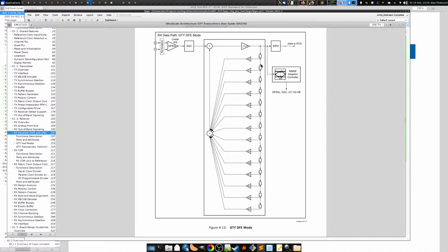Hang on a second. So what do you need for oscillation? You need some delay, and you need some negative gain, right? You need an inversion. If you have a positive gain, you get a positive feedback loop, it runs into the rail. If you have negative gain, then it'll oscillate.